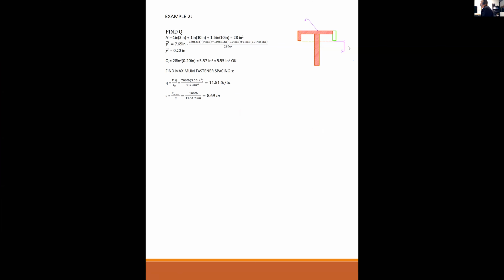I want to make sure I answer this correctly. I'm talking about nails that look like this. So the nail is perpendicular to the shear plane, and that's what's keeping the two pieces from shearing across each other. The force that we're talking about, q, is in the direction in and out of the page.